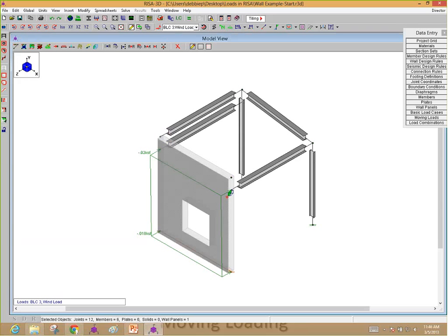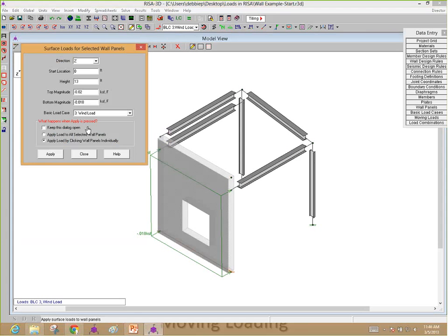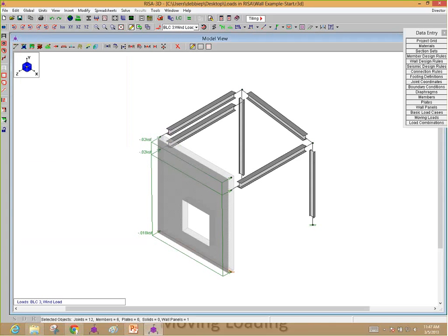And we can see it tapers it, and it doesn't go the whole way up. I kind of landed right where that parapet might start. So what I want to do is some constant parapet loading. So we'll go back in there, and we'll say 13 feet all the way up to 15 feet and negative 0.2 to the top. So we have 2 different types of loading on that structure.